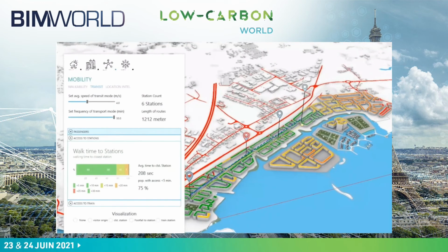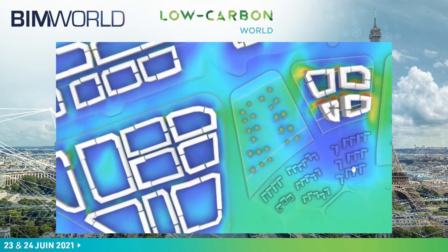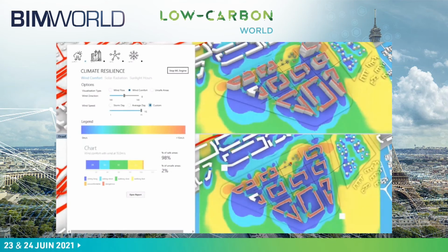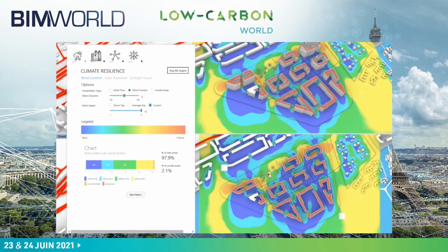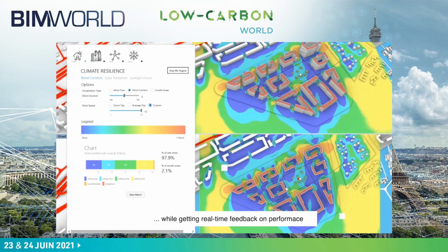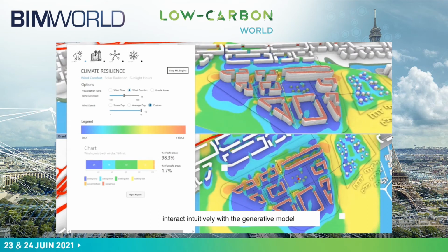In this case, we see, for example, Infrared working within Grasshopper, within Rhino, and we see a case study we did in Scandinavia, a waterfront development, where the designer can move around the park and immediately see the effect it has on the wind. You can see this updated in real time, along with the performance of that site on the left, showing how dangerous the winds can be in that location.